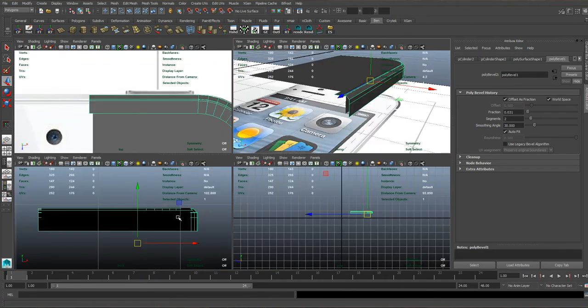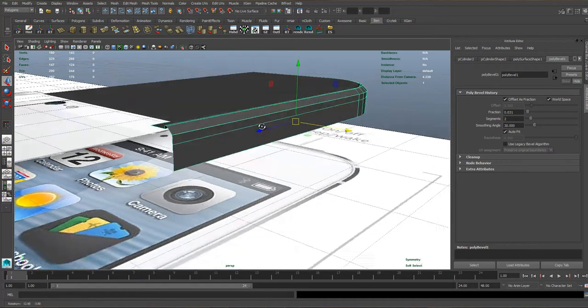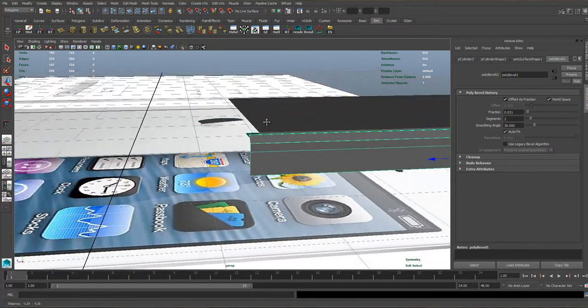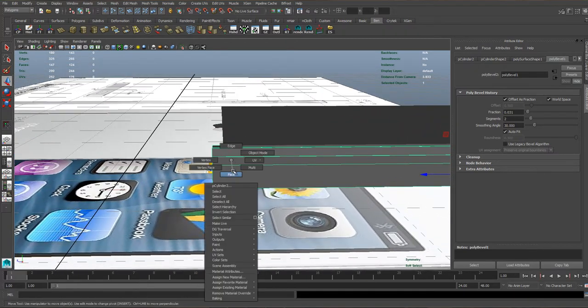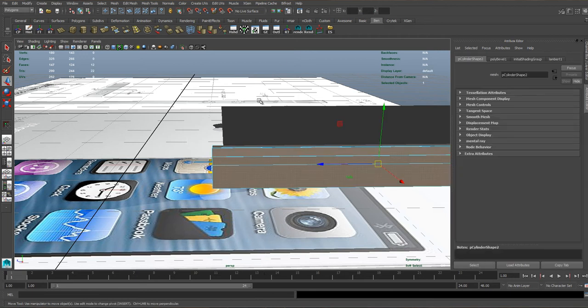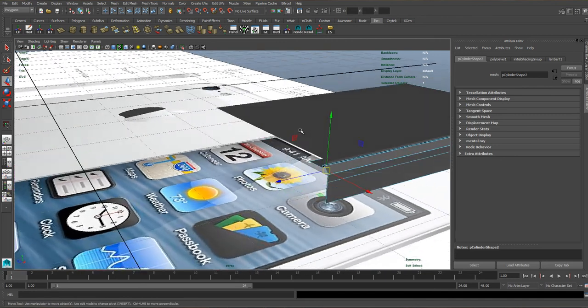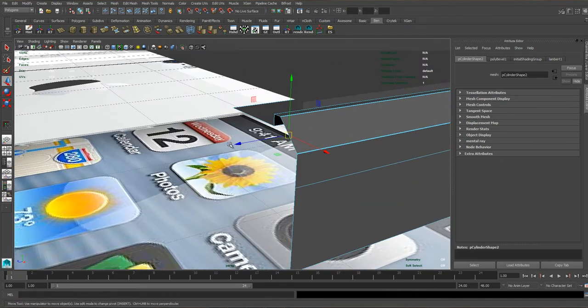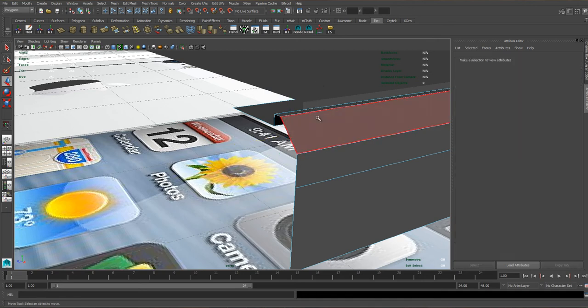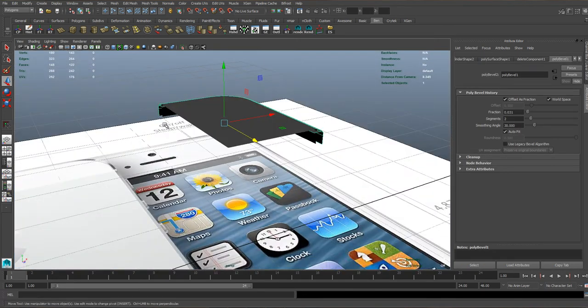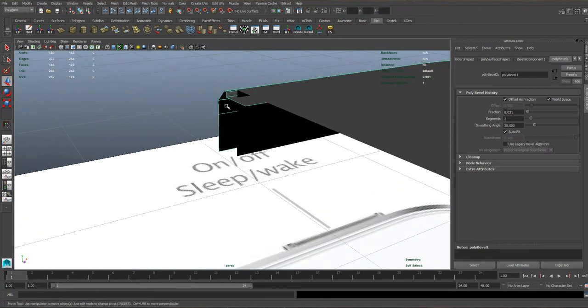And to delete them, because there's not much detail on this mesh yet, I can go to just around this view here, select face, unselect the faces I want to keep, which is obviously all of that. And these 2 tiny faces here will remain selected, and then I can hit delete, and they will go away. Again, you might not be able to see much there, but it has worked.